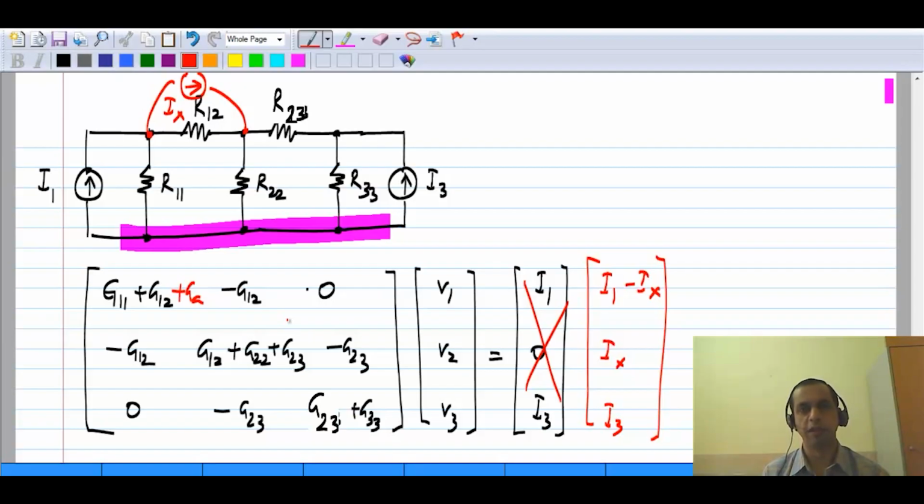Normally when you start off with circuit analysis, you look at the circuit and identify something as the important loop or node to start off with, or whatever is convenient for you. You start writing the equations in some ad hoc way, and finally when you have enough equations, you simultaneously solve them. But for large circuits, this won't work. We have a certain number of equations we have to set up, and we have to do it systematically. Nodal analysis is one way of doing that.